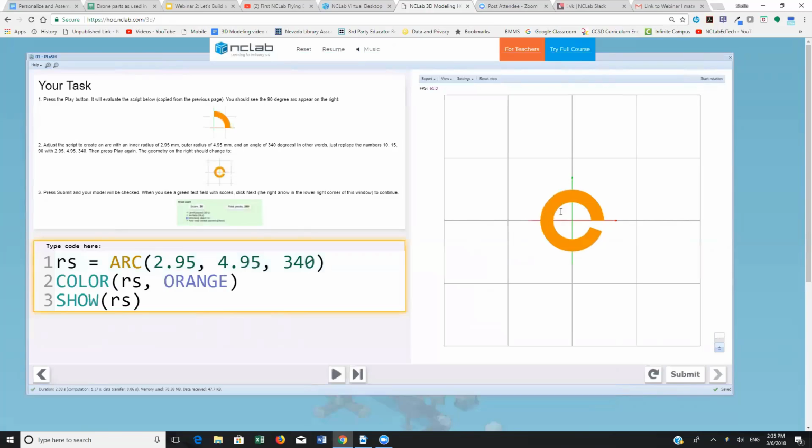When you put the motor in there, it'll fit very tightly. The motor is a 6mm motor. So the radius is 3 millimeters and this acts a bit like a spring. You push it in and then it'll hold it nice and snug.